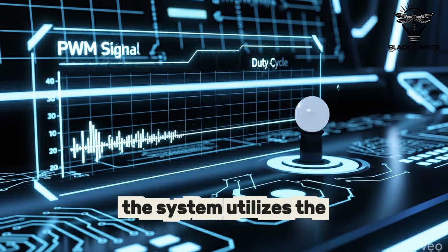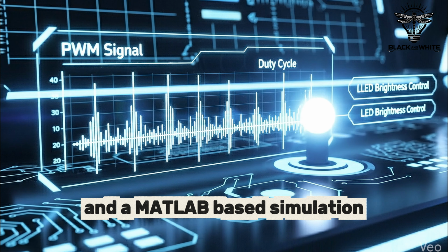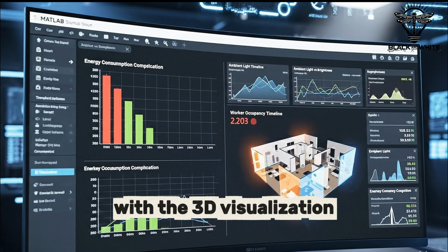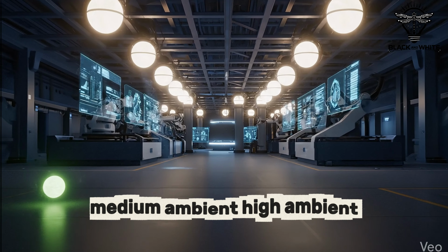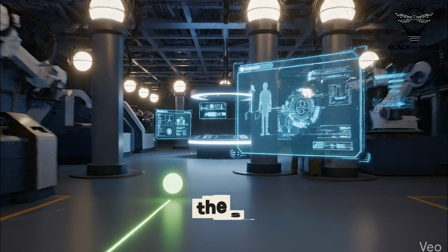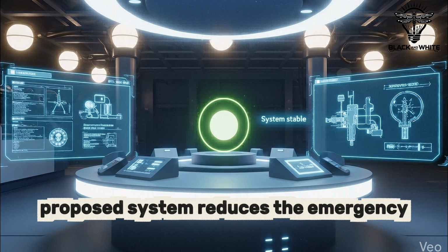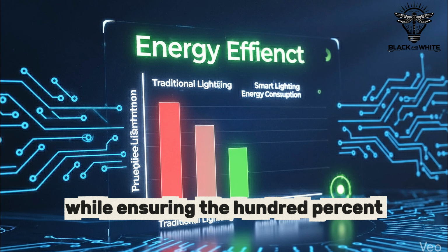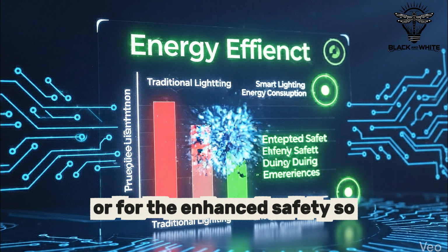The system utilizes pulse width modulation for efficient brightness control, and a MATLAB based simulation and scenario modeling framework with 3D visualization is developed to analyze different conditions such as low ambient, medium ambient, high ambient, rockfall emergency, and the gas leakage scenario. The simulation results demonstrate that the proposed system reduces the energy consumption under normal conditions while ensuring 100% illumination during the emergencies for enhanced safety.